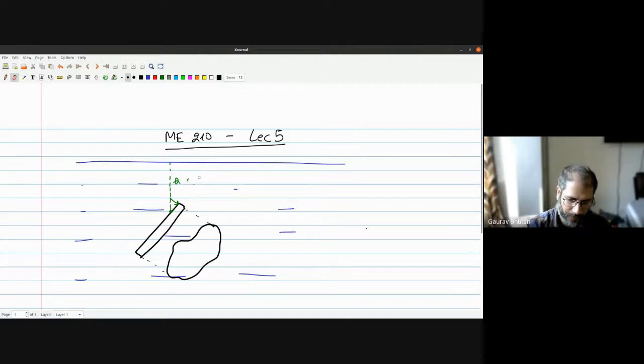Well, let's talk about x and y later. I'll tell you where the origin is. Anyways, as you go deeper, the height increases, and hence the pressure increases, and hence the normal force because the pressure increases. So we'll have some sort of a distribution of pressure which looks like this. I mean, the force because of pressure. Okay, so the job is simply to integrate these forces.